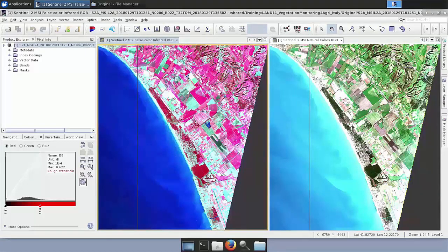And the second one is, or the first one actually, would be resampling. The subset would follow it, and the resampling makes sure that all our bands in the product are resampled to the same identical resolution. This is due to avoiding problems with many operators, such as subset, for example, that cannot handle multi-resolution data. So to do this, we will first build a graph.